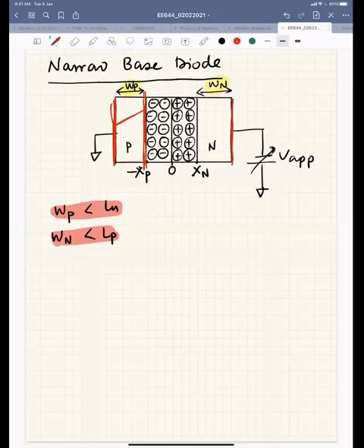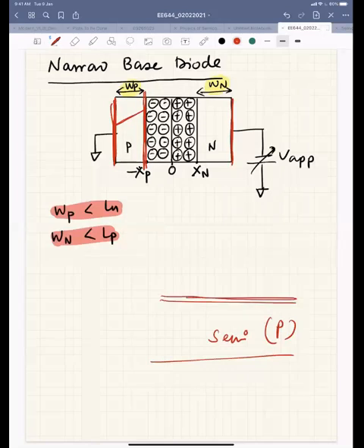Interestingly, this metal semiconductor contact has a lot of defects, right? Let's say this is p type, and I am depositing metal on top of it. We have also discussed the crystal structure, right? In a semiconductor we have a lot of dangling bonds, because each silicon is covalently bonded with four different silicon atoms, but since I'm cutting the wafer, we have some dangling bonds.